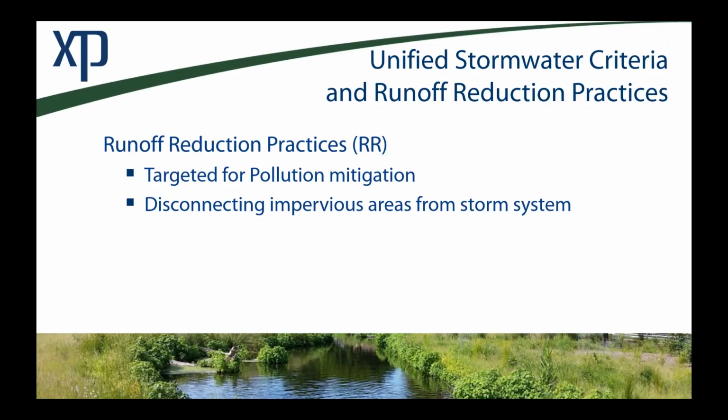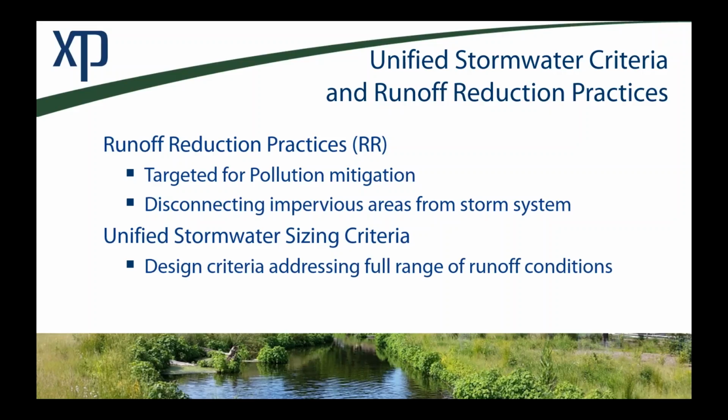Runoff reduction is what we use to talk about sizing specifically our green infrastructure, our pollution removal facilities. So what is the unified stormwater sizing criteria? Well, it's the runoff reduction and everything else. According to the Georgia Stormwater Manual, the unified criteria method is an integrated set of design criteria for stormwater quality and quantity that addresses an entire range of hydrologic conditions.